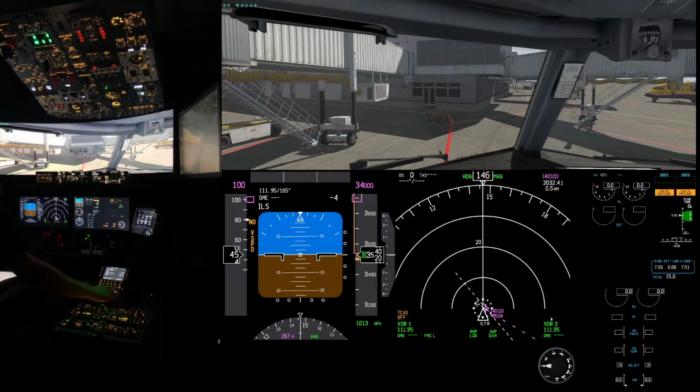Moving on to the next page, I'll look at my outside air temperature. It's showing me here a warm day today, 27 degrees in Calgary. And it'll show me the percentage of N1, which is the percentage of thrust, and it's 100.6. So I'm going to leave that as it is right now. That's at the full 26K.